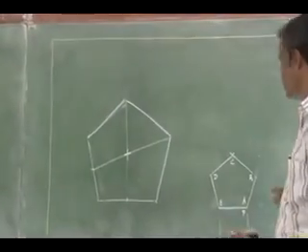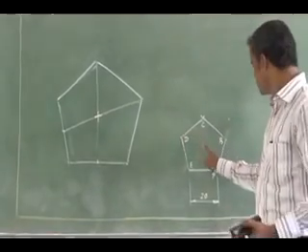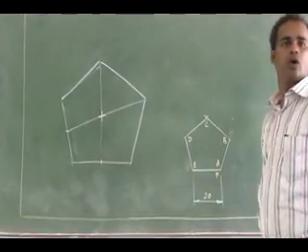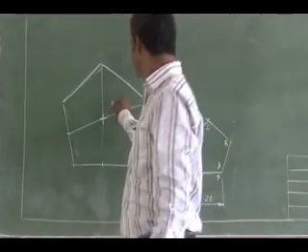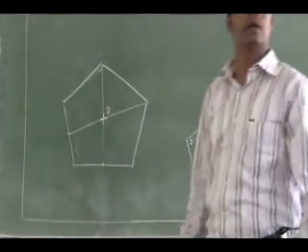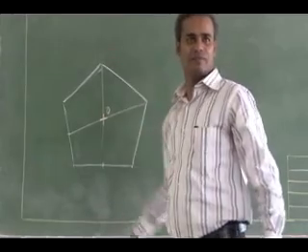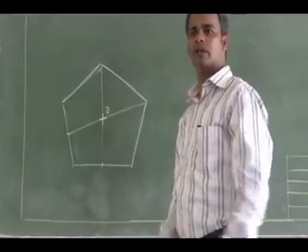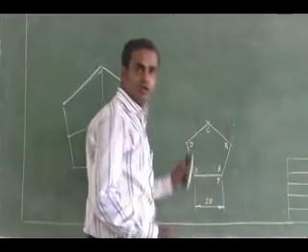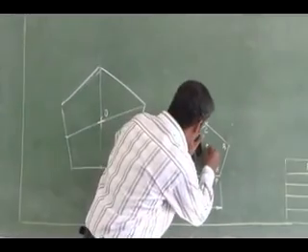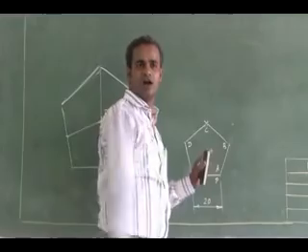So this is like my center. Normally the center of the pentagon will be below these two corners, somewhere here. This is how you have to mark the center of the pentagon. You need not draw all the way, you need not draw this line. You have to get the middle. So you can mark the middle, fix your drafter, and get a line in the middle, vertically, joining to the opposite corner.